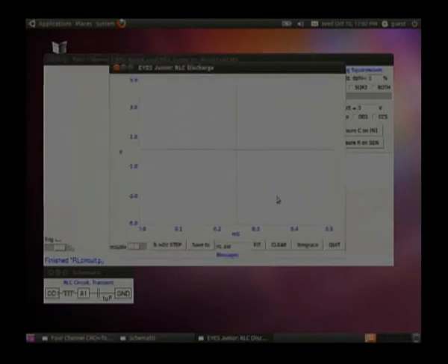Here we have the pop-up window, and we give a 5 to 0 volt step. It shows something like this: it goes to negative and tries to build up. Let us change the time scale a little bit and repeat it. You can see that when we gave the 5 to 0 volt step, the voltage across the capacitor comes down, does a couple of oscillations and dies down. So, this is the response of an LC circuit, basically an RLC circuit, because the resistor is always there.